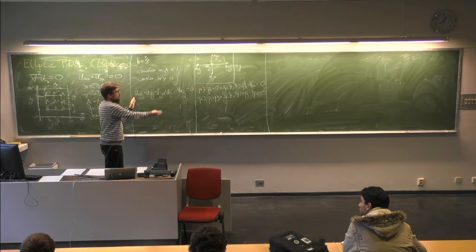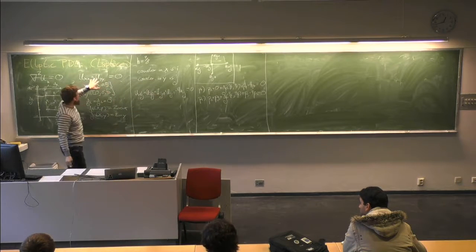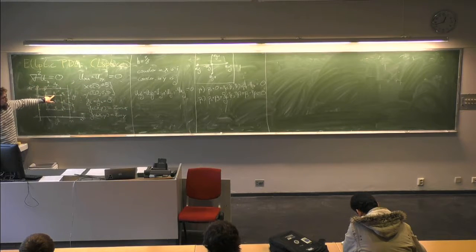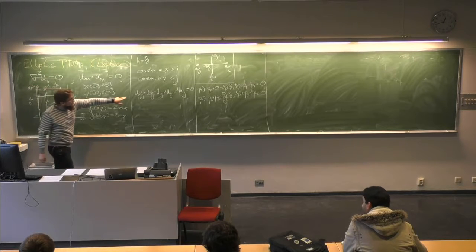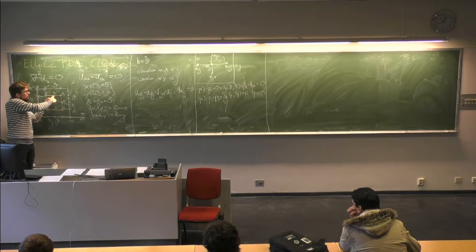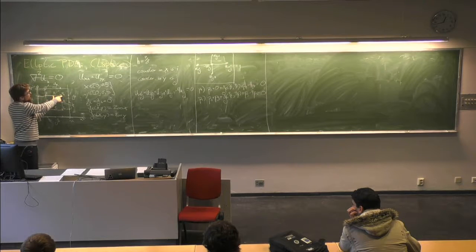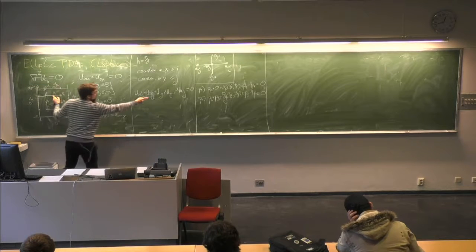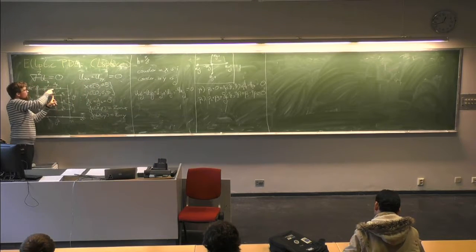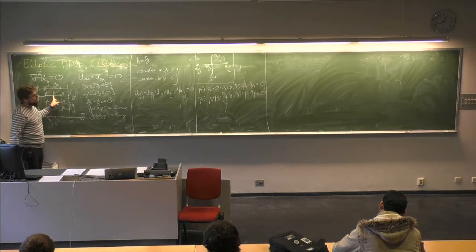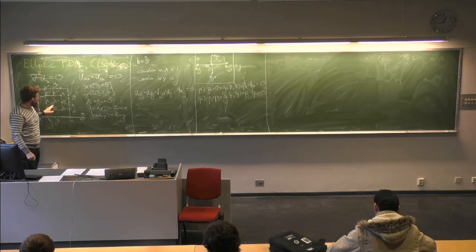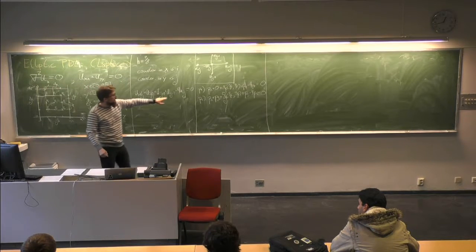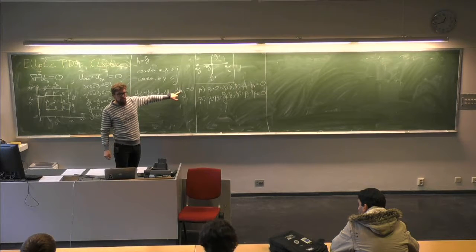Okay, so I'm just solving this equation. That's the discretized version of the Laplace equation over here. So I'm looking at solving P2. Well, for P2, I need i plus 1. So i plus 1 standing in P2 is going to be at this point, and then minus 1 is P1. Then the next one is i, j plus 1, that's the one above it. Then you get the P3. Then the one below it is P5. That's this. Then you have the point itself, 4 of those.